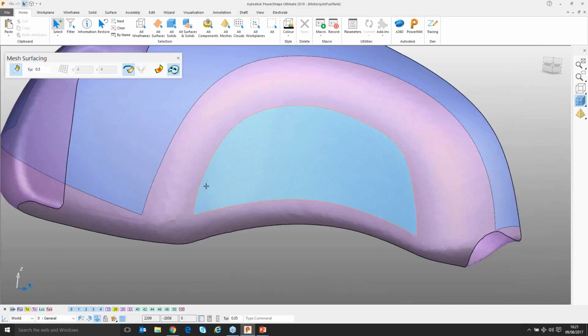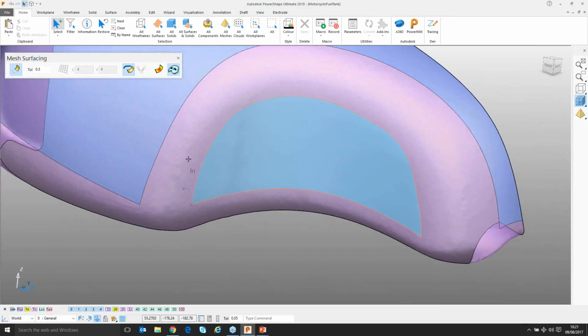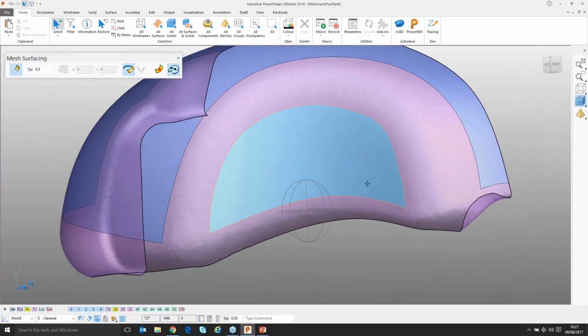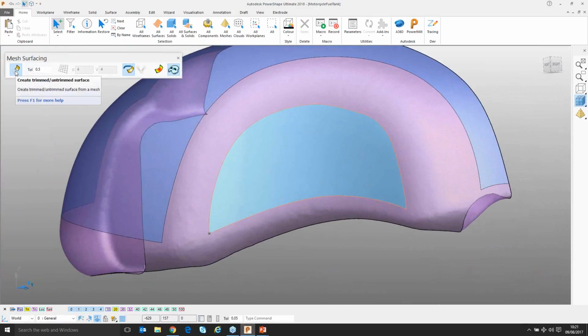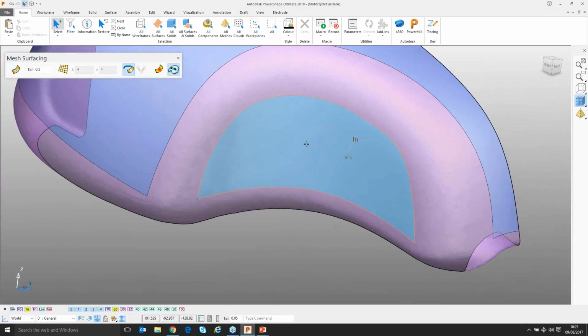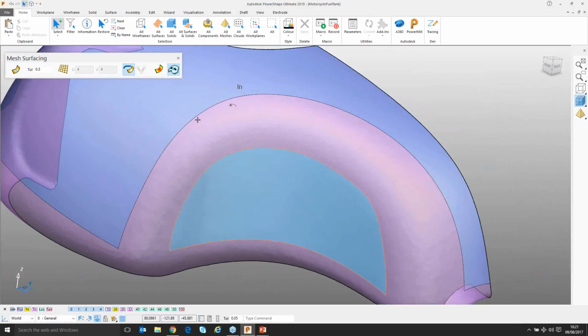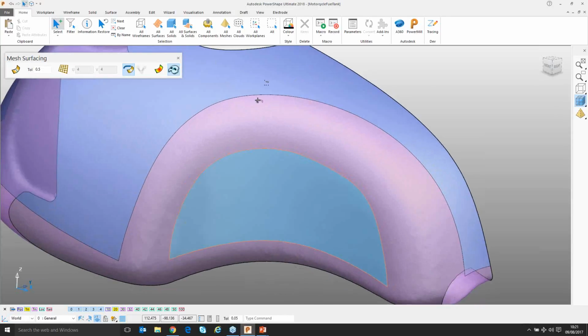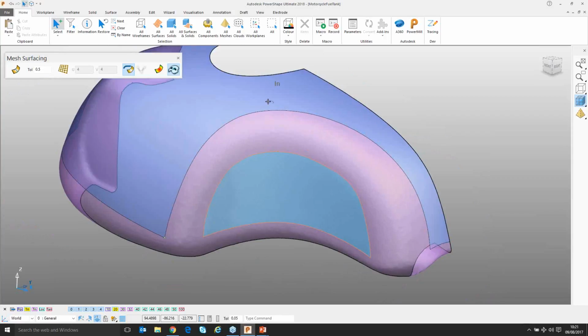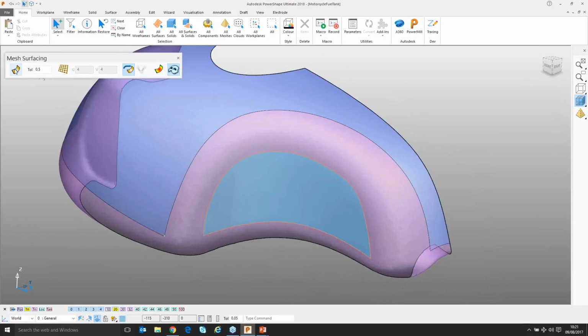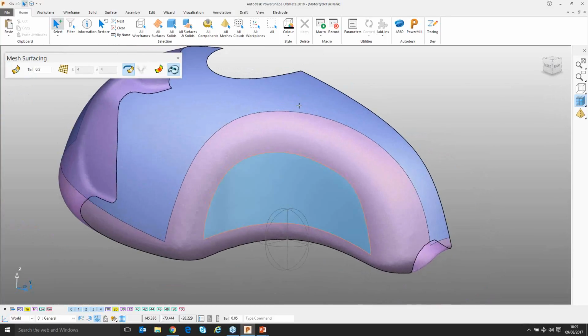Okay, so now I'd like to put a fillet that really combines these two. And for this, I choose to use a non-trimmed surface because the difference here is we're not using trimming data over a large blanket to get the edge. We're actually using the edge of the surface itself, and that gives us a much better match to surrounding surfaces. So again, my working method is to put the large blanket surfaces in using NURBS, trimmed regions, which are really, really smooth, and then connect those together using non-trimmed surfaces, which can hold the edge of the surrounding surfaces as good as I want it to be.